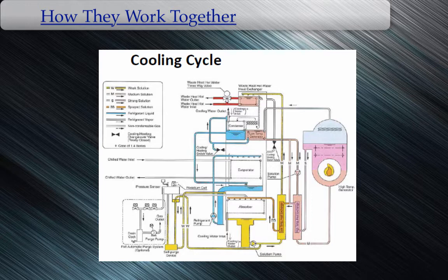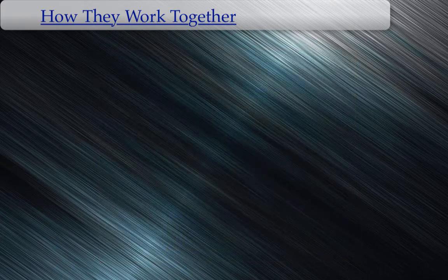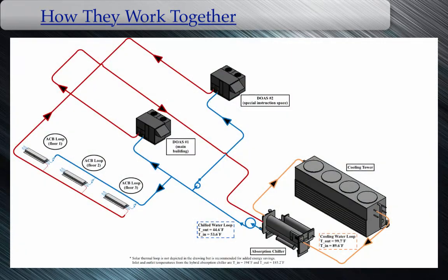Another method considered that could reduce the gas consumption rate even further is utilizing solar thermal flat plate collectors on the roof of the building. Depending on the time of the year, the need for clean natural gas could be completely eliminated. The low temperature generator has the ability to operate at 57% of the total cooling capacity, which is equal to 85.8 tons of cooling.